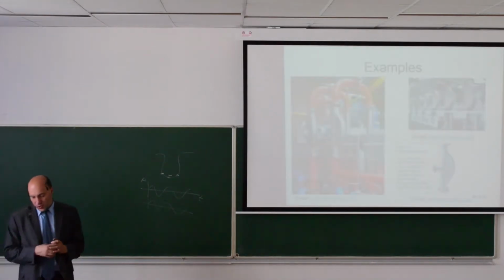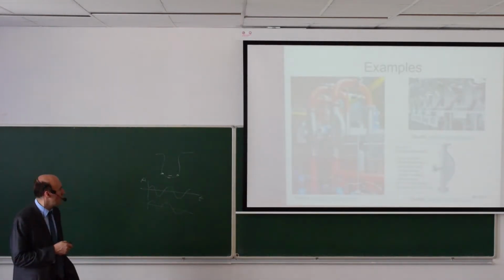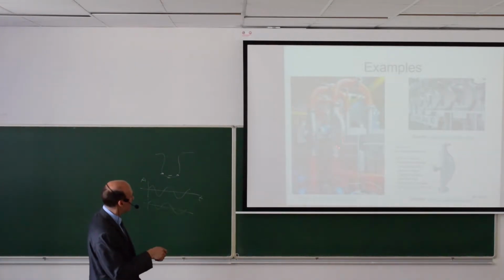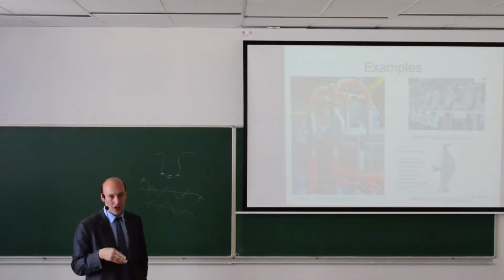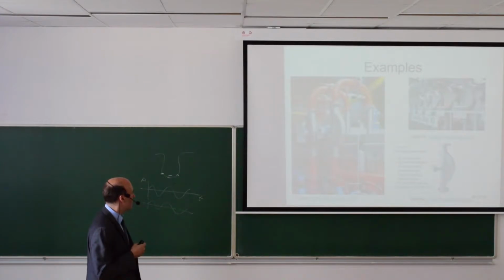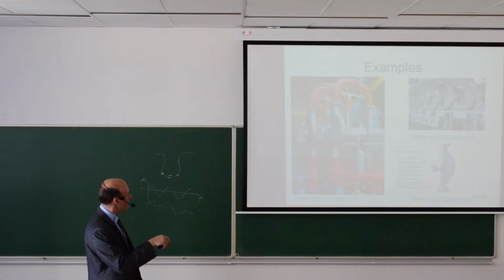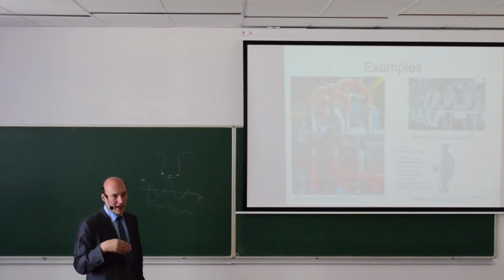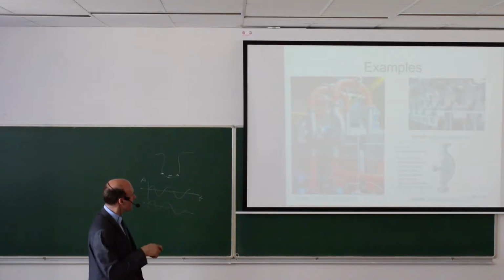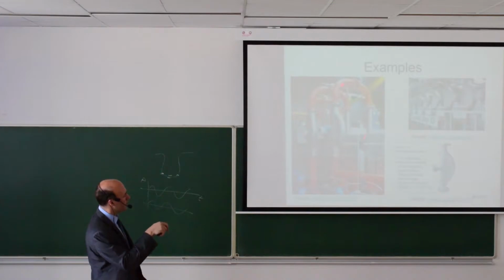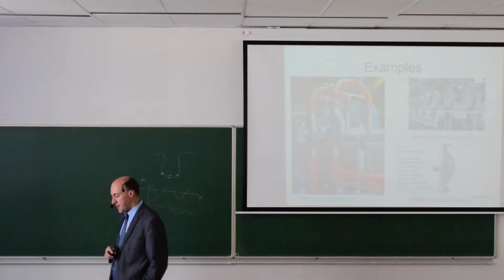Here are some pictures of installations. So you see the typical shape. This cover hides the bended tube so that we are able to measure the Coriolis force inside. And from the picture that will follow, we will learn that the flow rate will be from bottom to top, since this needs to be filled again at all times. So here from those pictures you can say, okay, the liquid is pumped from the bottom to the top like this through the flow meter.